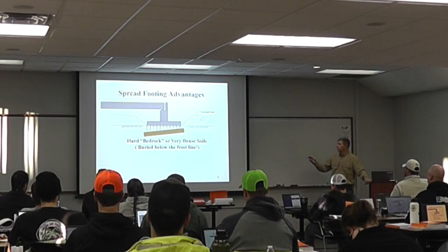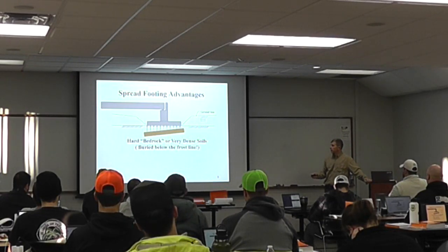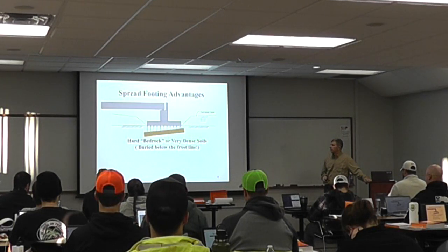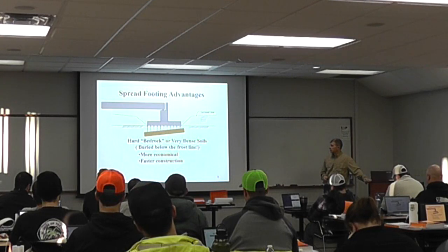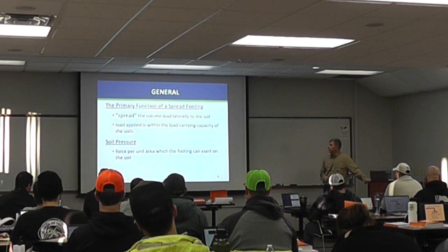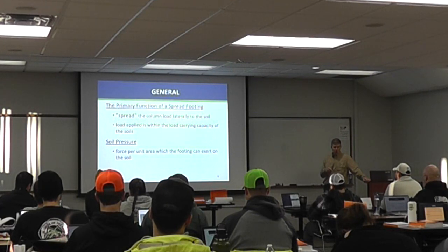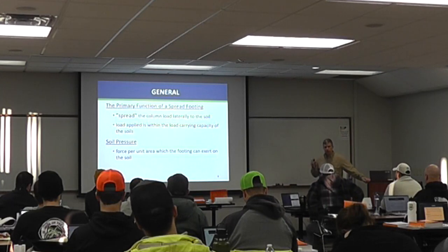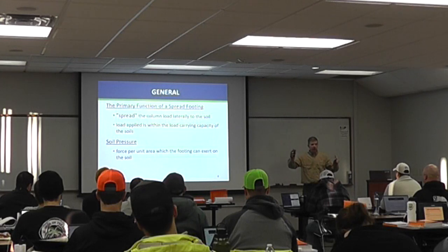So if there's hard bedrock, very dense soils, those are a perfect way to use it. It's going to provide a good support. And so they are more economical, they're faster construction, and it simplifies the process. So you're not in there having to stage a pile rig and so forth. The primary function is to spread that load out among the footings. So the footings are designed to kind of balance.